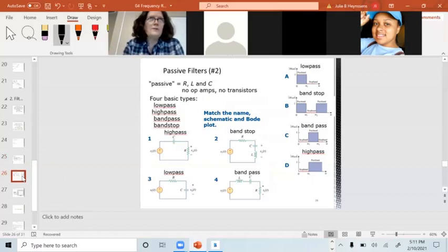These filters, and we've already talked about low pass filters and high pass filters for audio circuits. The ideal low pass filter, and I labeled these today because I was tired of the guessing game. A low pass filter, the ideal filter, which you can't build by the way, has a gain of 1 inside the pass band. And when I get to this omega naught, after that, it has no gain whatsoever. That's ideal, and we can approximate it. The easiest approximation is a simple RC low pass filter circuit.